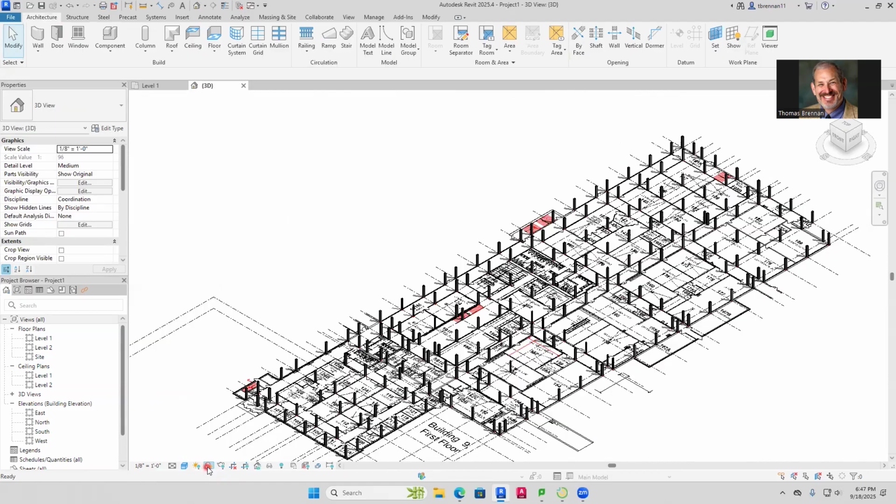The next thing we're going to do is start to put the walls in. Again, this is all going to be practice for placing walls, because as we go along, we'll be doing more of this stuff. Placing walls can be a little bit more ticklish because you never want to put walls on top of walls, because Revit doesn't like it. You can do it, but then they get double counted, which makes your model incorrect. Even though it lets you do it, it's going to gripe at you.